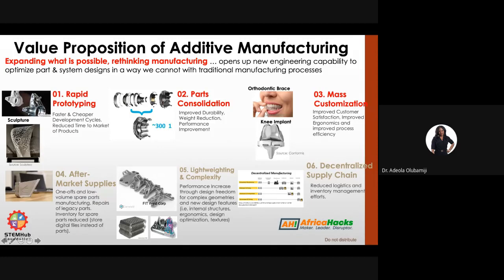Another thing is durability, because when you weld parts together, those areas can also be your crack initiation point. If any crack is happening, that could be the first place that will crack, because you welded the two parts together, and mechanical properties at joints are oftentimes the weakest. So with this, we've been able to have better durability. So parts that used to last for 5 years, we now see them lasting for 10 years, for 12 years. In some cases, we're seeing them even lasting longer than that.